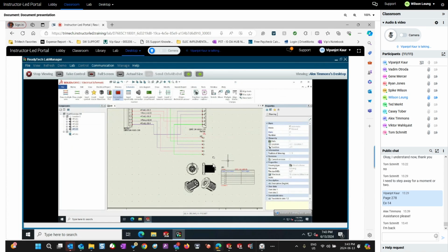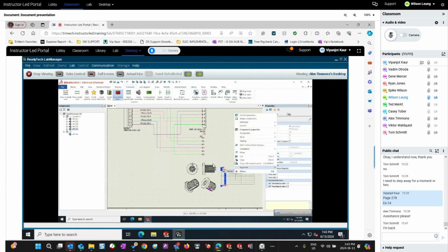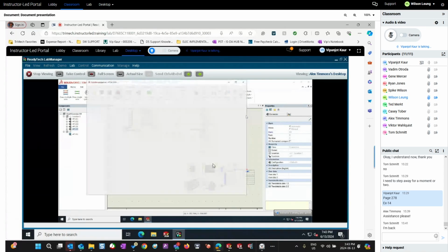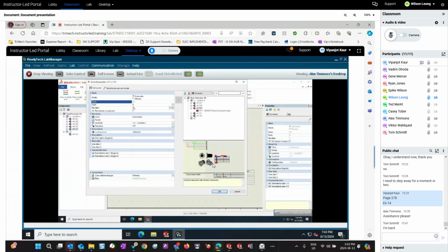So how do you think the table symbol can be linked to the second terminals that you dropped? Right click on this table symbol, link it with your component X2. How would you change the component? First button, symbol properties. It's a property of a symbol. Link it with X2 component, so that this table is for X2 connector.